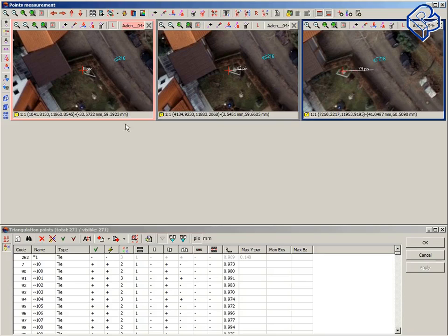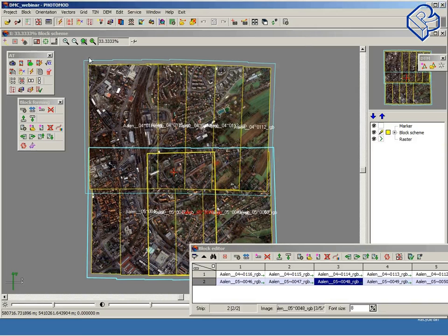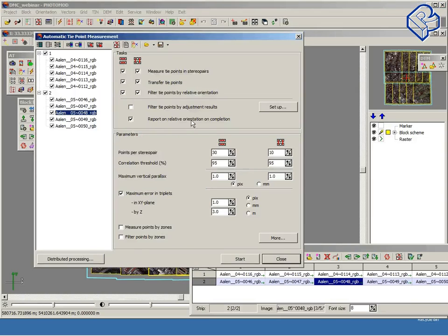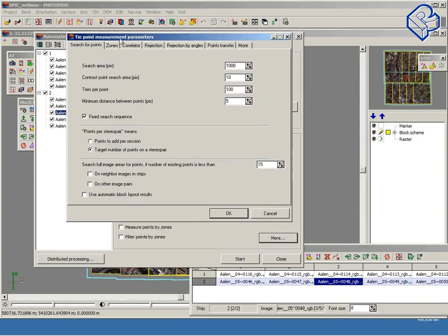And I say that for these three specific images, the biggest search area that the correlator algorithm will need is 80 pixels. And when I start the process, I should set up this parameter accordingly. So it shouldn't be less.